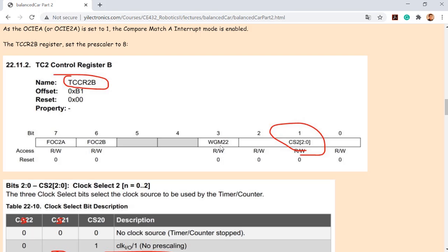Since you know the clock frequency is 16 megahertz, if you design a counter, it's going to be a timer. Since you know every count is 1 over 16 mega, you know how many counts will be 1 second. That's how you can design a digital watch, because you know it's 16 megahertz. It's not being connected to anywhere, right? It's just running independently by itself.